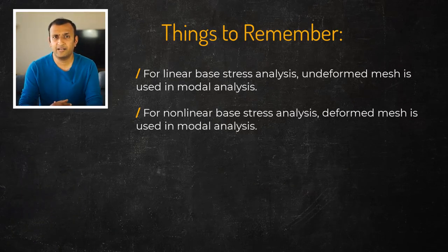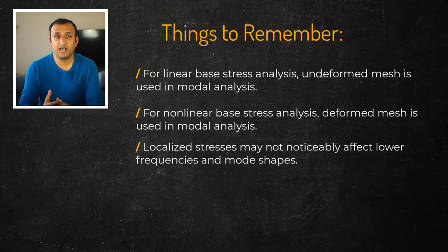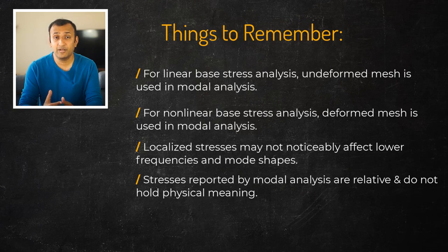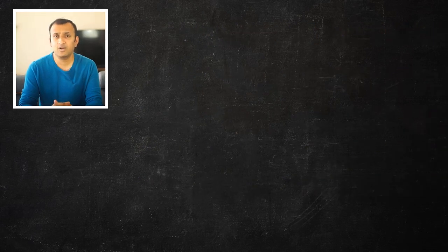It's worth noting that the presence of stress may not always affect the mode frequencies. For instance, if the stresses are localized, then they may not impact the system's frequencies at lower modes. Also, the stresses reported by a modal analysis are relative, and their absolute values do not hold any physical meaning. Now let's go ahead and see how pre-stressed modal analysis is done in Ansys Mechanical.